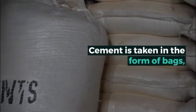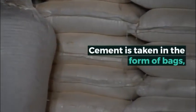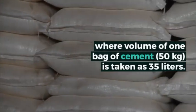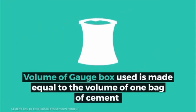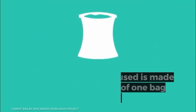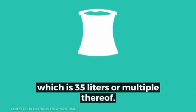Cement is taken in the form of bags, where the volume of one bag of cement is taken as 35 liters. The volume of the gauge box used is made equal to the volume of one bag of cement, which is 35 liters, or a multiple thereof.